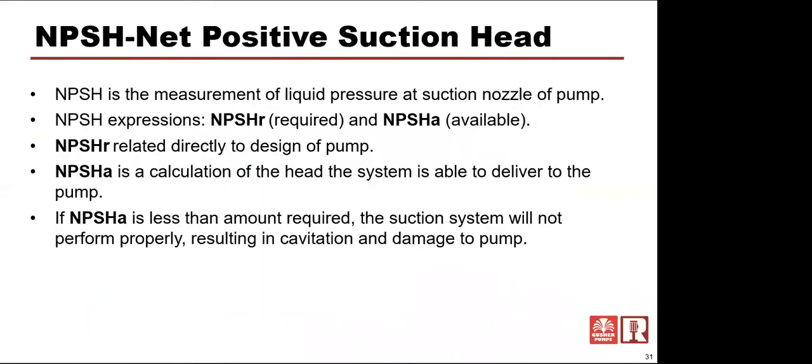Appreciate it. Okay, so let's start talking about net positive suction head. And this is one of those vernaculars that I hesitate using, but it's the most accurate way and the way pump manufacturers and pump people know what to talk about. Basically, it's the amount of pressure that fluid has at the inlet of the pump.